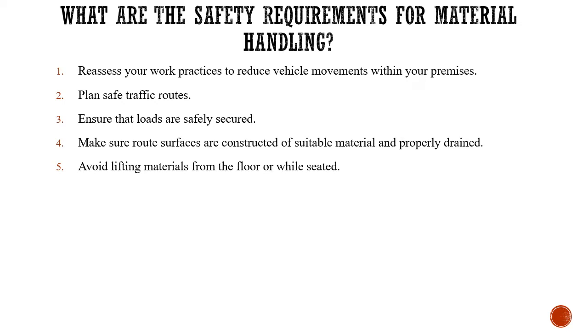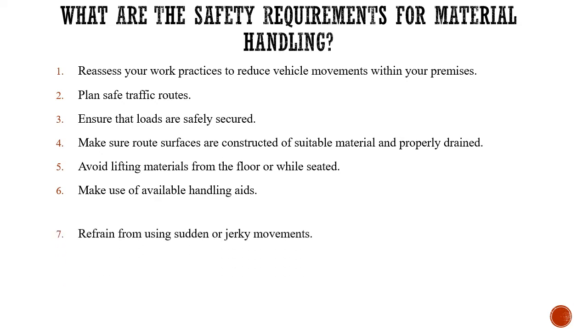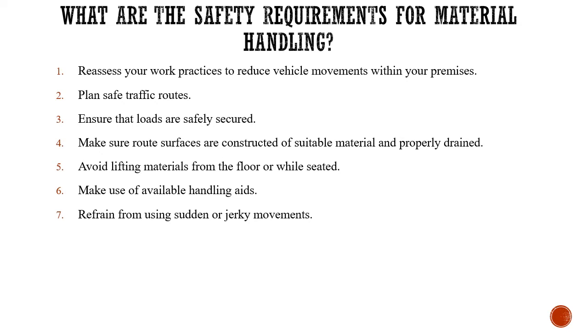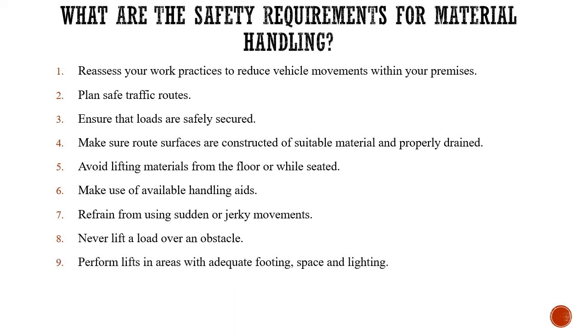Avoid lifting materials from the floor or while seated. Make use of available handling aids. Refrain from using sudden or jerky movements. Never lift a load over an obstacle. Perform lifts in areas with adequate footing space and lighting. Modify objects and redesign jobs to make moving easier. So these are some of the safety requirements for material handling.